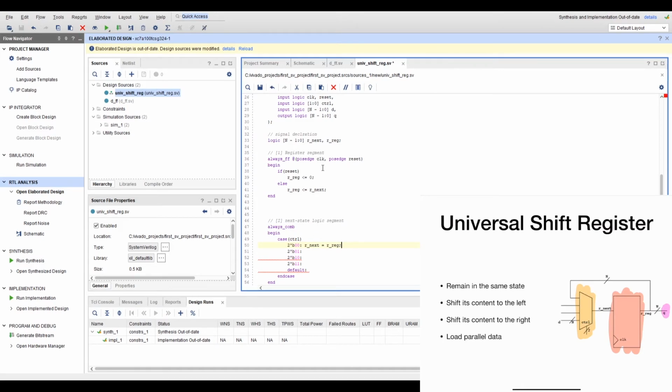And as you can see in the upper one, in the always_ff here, I use non-blocking assignment because this is a sequential part. And in this part here, which is part 2, I'm using an always_comb, so all the assignments have to be blocking assignments, because it's a combinational circuit. Okay, that's good. So then we do our next in here.